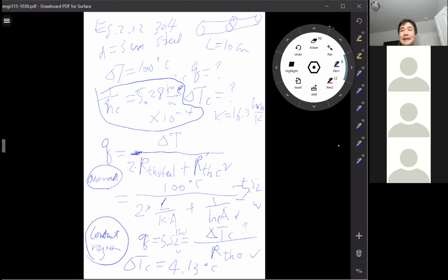Then it's up to you how to find each resistance from convection, conduction, and radiation. That will all be different, but those are individual sub-problems. Otherwise, if you don't introduce this, your overall equation will be more complicated when conduction, convection, and radiation are combined.